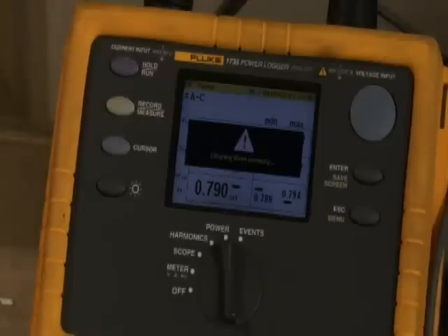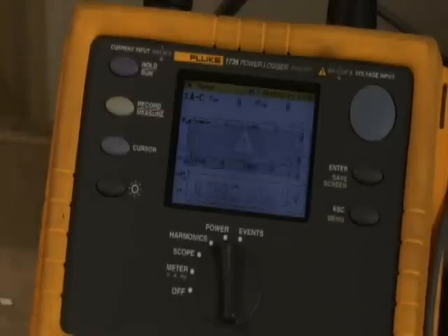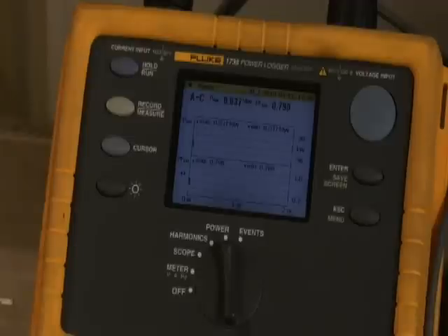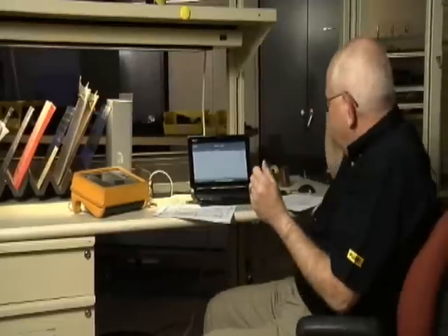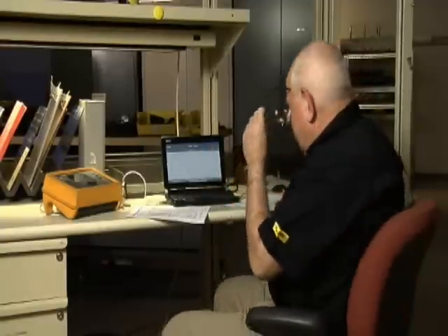Notice when your peak demand occurs and compare it to your operational schedule. These charges can be managed effectively by analyzing the data from your power logger. When you're done with all of your logging and you've downloaded your data from your power logger into your computer, sit down with your utility bill and your operating schedule for that same period. Here are some things you need to look for.